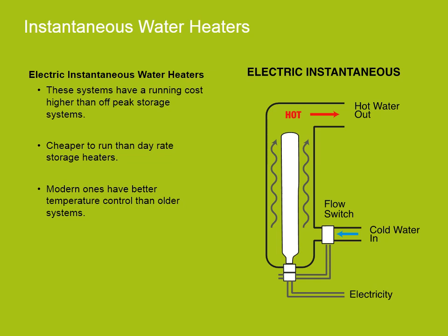Electric instantaneous water heaters have to be linked to the day rate tariff, resulting in an increase in the running costs compared with an off-peak storage system. On the other hand, since there is no tank to lose heat, they are cheaper to run than day rate storage heaters.